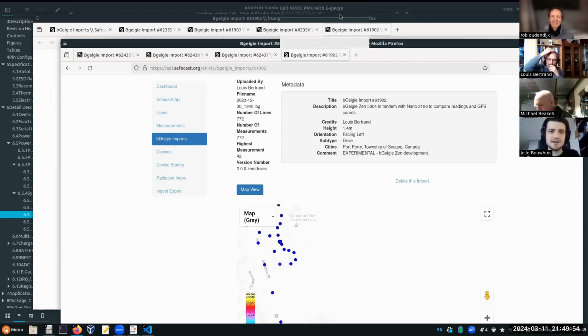Currently the M5 library doesn't have a way to check which one is connected. It has all these helper functions, and if you look at the implementation, internally it knows because it's a private property which one is started or connected. But you can't really do a check like, is this one connected? Yes, then write this register. So if you write the code, you have to only test it on the Core 1.1, I guess, or the Core 2.